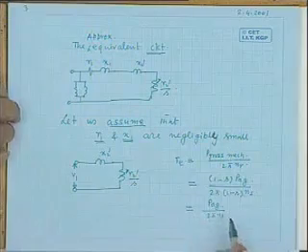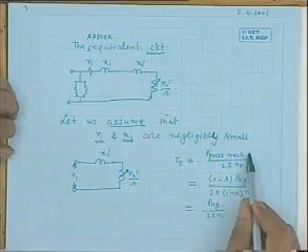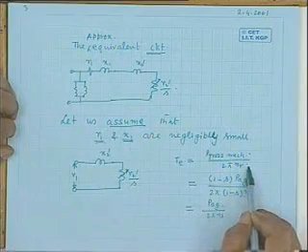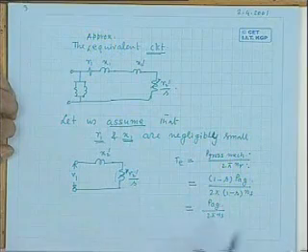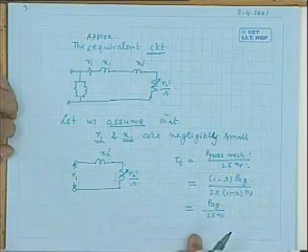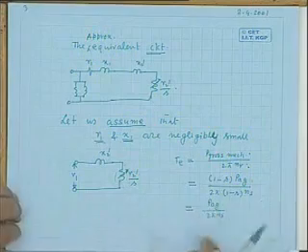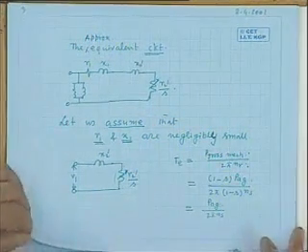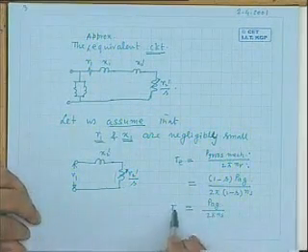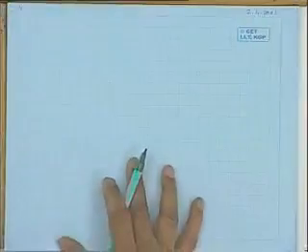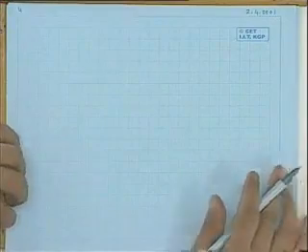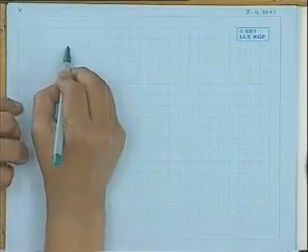So to calculate electromagnetic torque, you can calculate gross mechanical power and divide by 2 pi Nr, or you can simply calculate the power here and divide by 2 pi Ns, synchronous speed. Either way you do, it is correct. So we will do it this way because it is simpler. We will calculate the air gap power in this way.